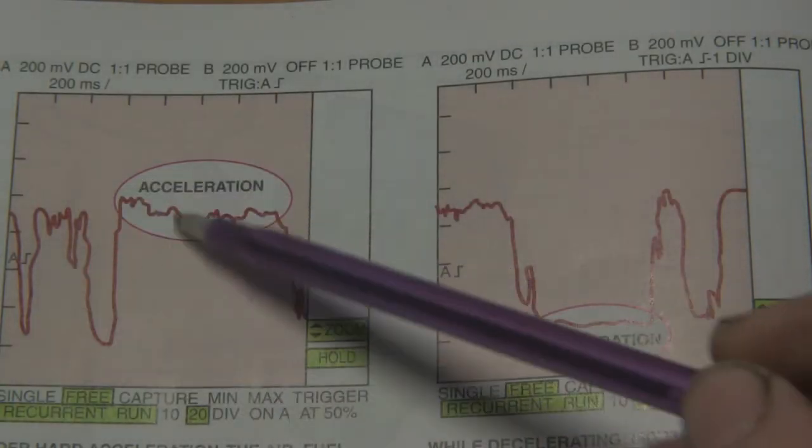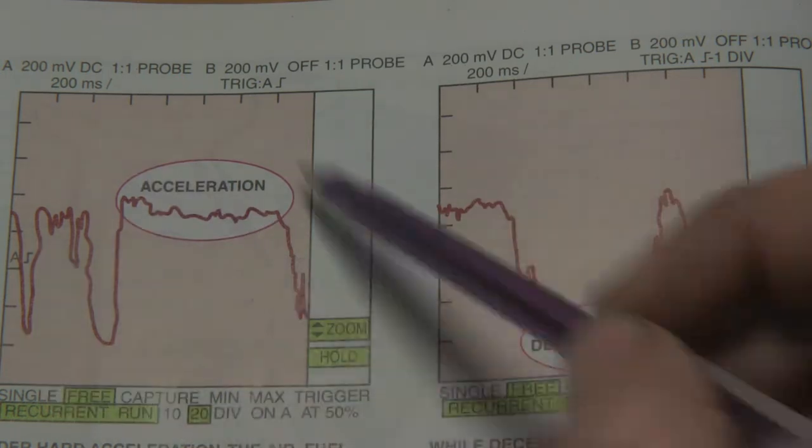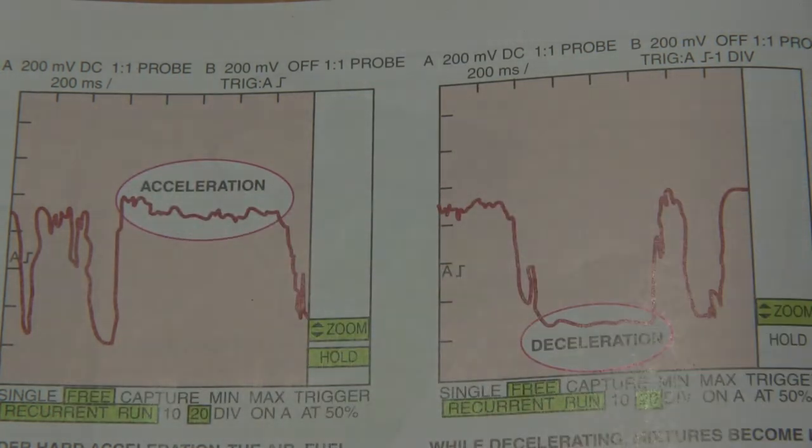So you look at your scan tool data, and you see this upward spike when you go to full throttle. That, in and of itself, is normal. It should go up. Why does the car stop misfiring? Why does the car start to run better? It's because one of those inputs that the computer is referencing for fuel delivery is bad.